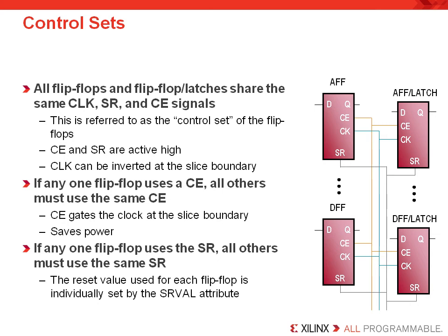We don't suddenly find that we have less device utilization by building that. But the key thing here is that this is done on the slice level. So if you are developing low fan-out control signals that maybe only drive a few flip-flops, then you should be able to find the tools to group those flip-flops into the same slice to reduce the number of control signals that are distributed through your design.